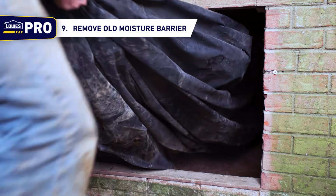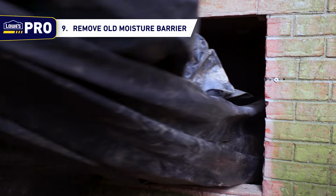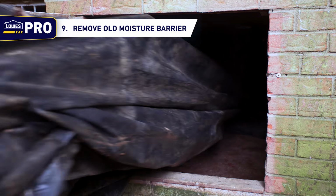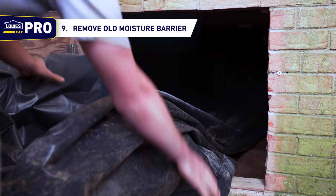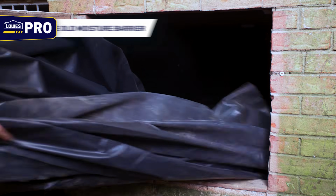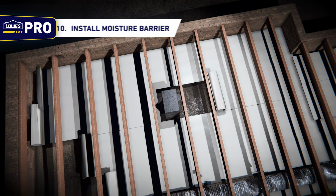Step 9. Remove old moisture barrier. After the repair and mitigation work inside the crawlspace is complete, remove the old moisture barrier, if there is one, and create a level surface area so you'll be able to properly install the new moisture barrier.